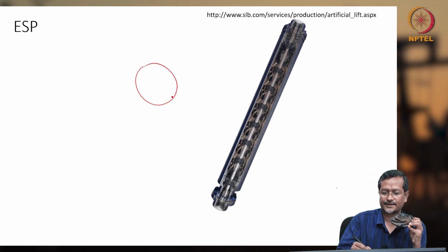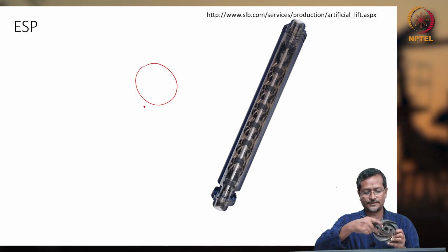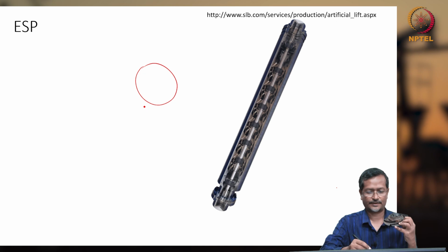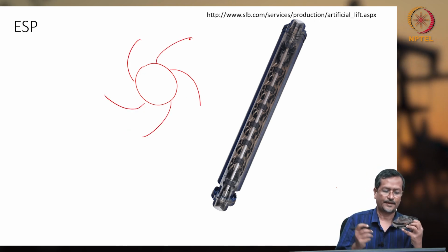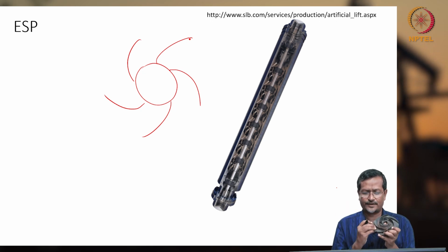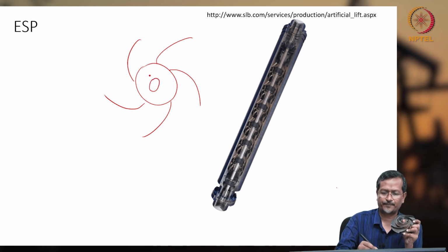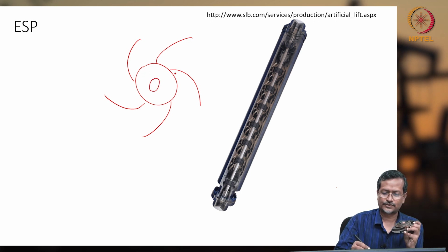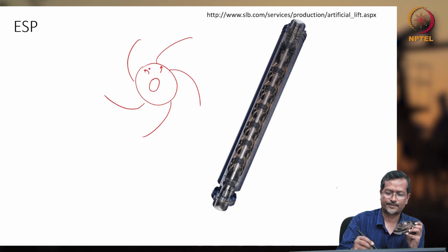Impeller eye is here, and my impeller, if I draw like this, it is having a curved blade, right? So blades will be 5, 6, 7, within that range, not like 100. Okay, now there will be one shaft hole. So fluid is entering through this gap. Actually there will be some gap. So this is called the impeller eye,